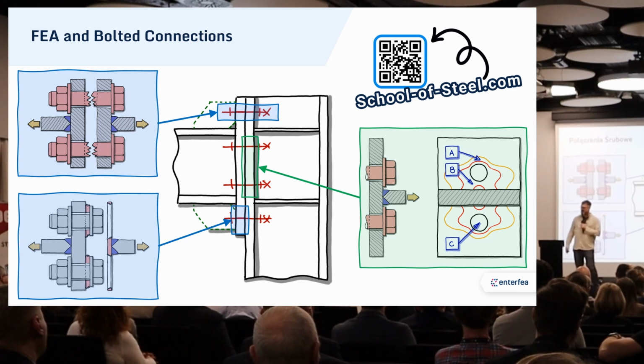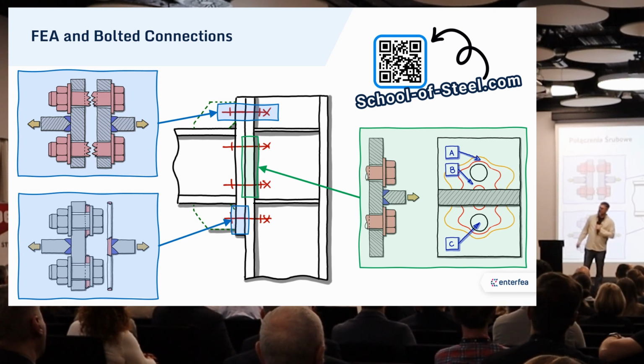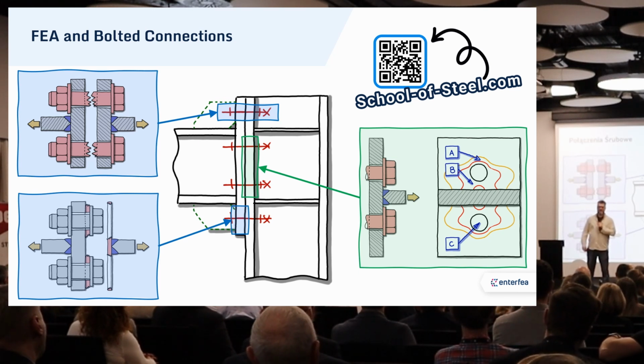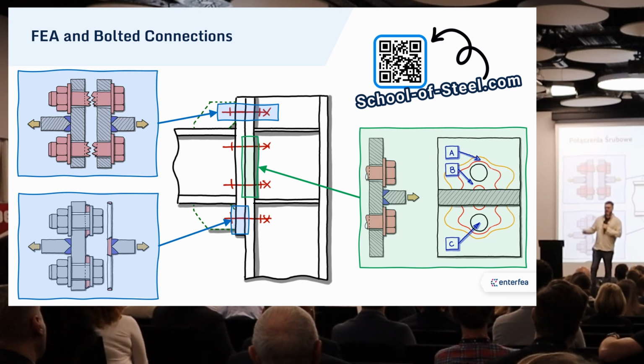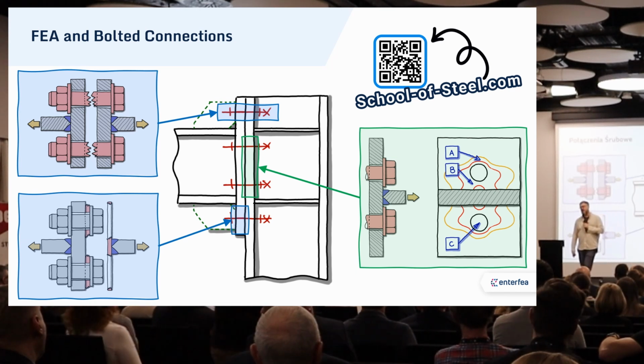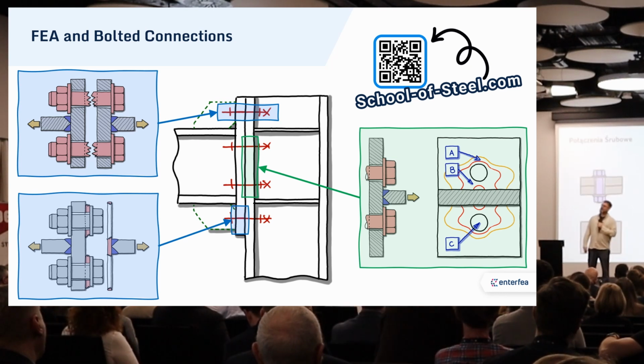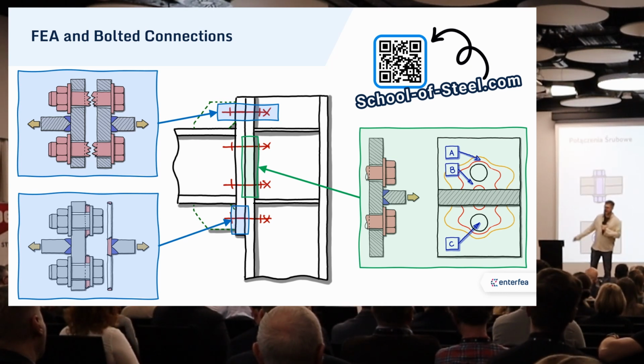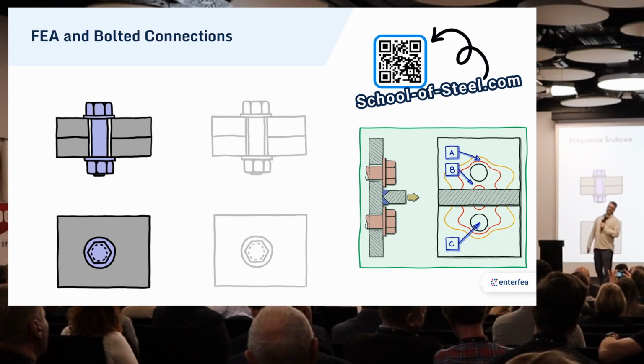If you would connect the plates simply by a single node with a beam element, the problem is that the stress peak there would be so high that it would seem that your plate failed. So you need to have a solution that has a reliable way of distributing stress around the circumference of the bolt in a more reasonable way. And to do that, you can model the bolts like this.